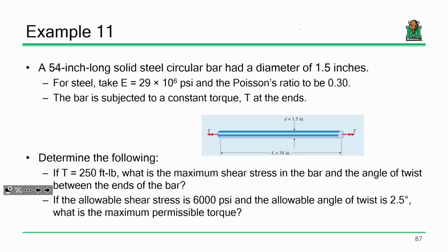But it's something very common in the world of engineering. I can't tell you how many structural engineering problems we have where we design for moment capacity and shear capacity, but what governed our design, what dictated how large that beam would be, were deflection requirements. The beam was perfectly fine to resist the moment and shear, but because it couldn't deflect too much, that's what limited the design. So that happens quite a bit. All right.